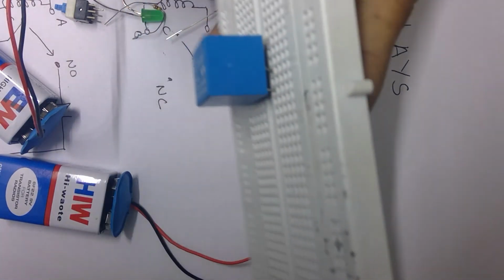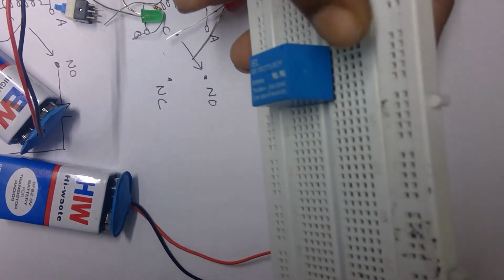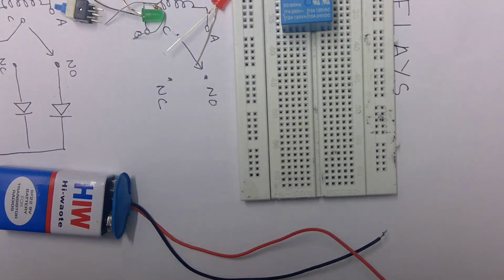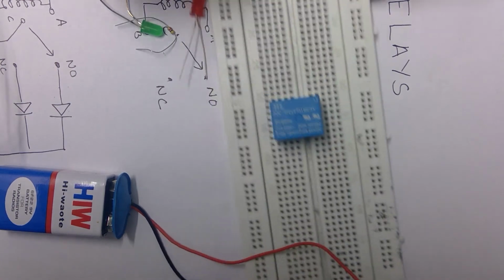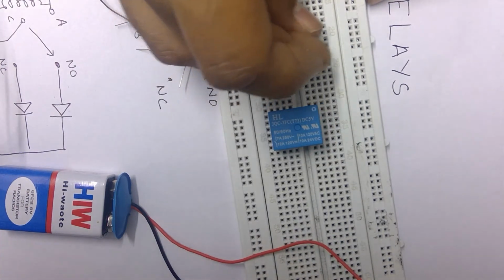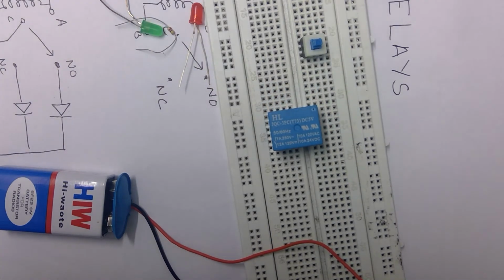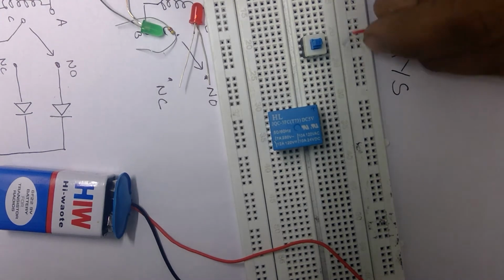And we're going to pick up points and just leave a slight gap so that we know where those points are and we can use it at a later point of time. Now we are going to connect our switch. So let's take our switch and we will place it somewhere here. Now let us give power to our switch by connecting our 9-volt battery source.